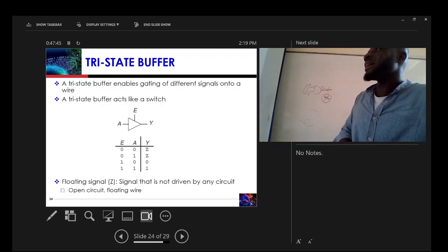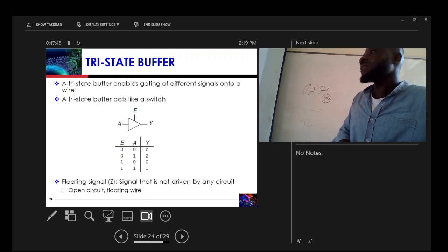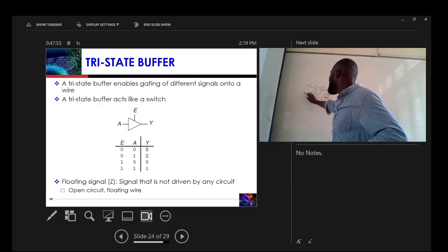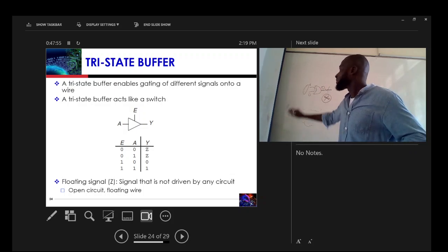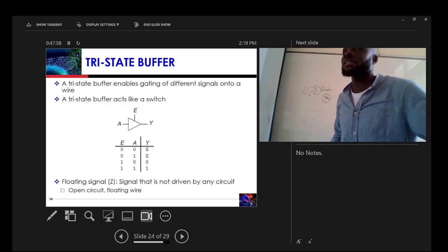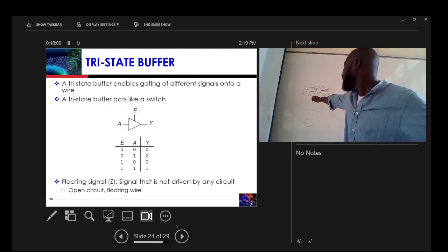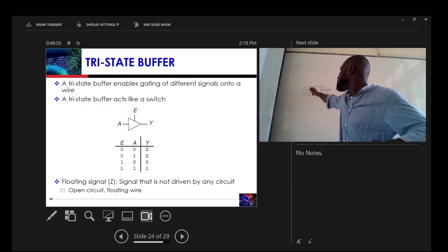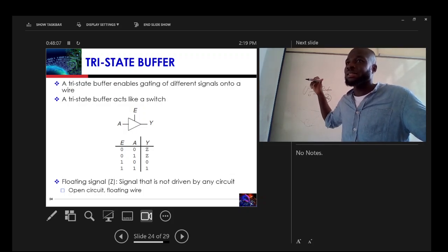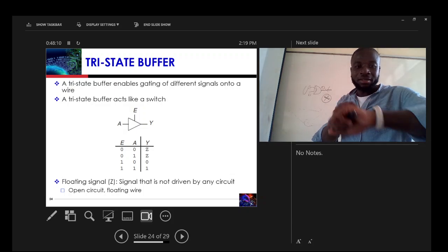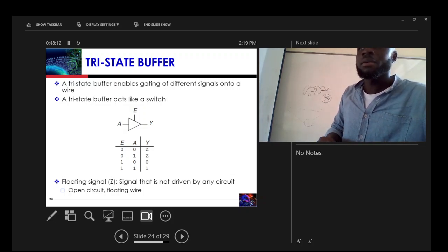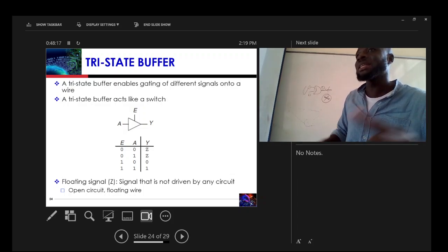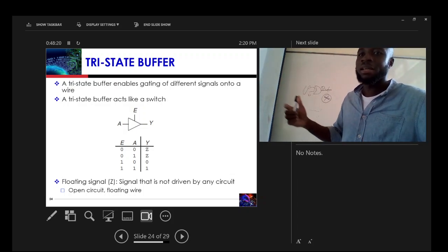There are several cases. For instance, if you have an OR gate and you give one of the inputs 1 and leave the other input out, the output of the OR gate will not depend on that value. So this value is either a 0 or a 1, but you don't know which. So anytime you connect an input, it's either 0, 1, or unknown. Unknown just means 0 or 1, but you don't know what the value is.